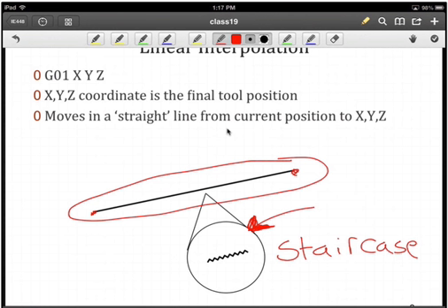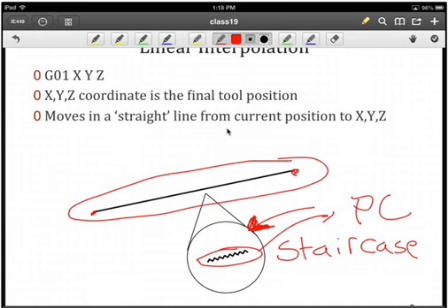because of the machine control. And so we're not exactly getting a line. There is some degree of variation from the line, and so this is going to contribute to our process capability. The degree of this staircase effect, of course, will depend upon the resolution and the precision of the machine tool that we are using. And so it's always good to know to what extent this occurs for your specific tooling. And that's usually in the design spec and description of the machine tools.